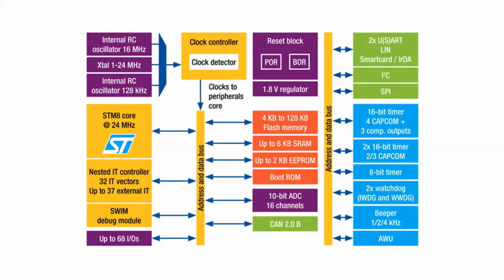As you can see here, we've got things like UART, I2C, SPI, CAN bus. These might be a bit unfamiliar to you, but as you go through working, if you get a sensor which you need to interface with over I2C, which is actually what we're going to be doing in the coding demo later, you can easily interface with that through this I2C controller that's already on your microcontroller.